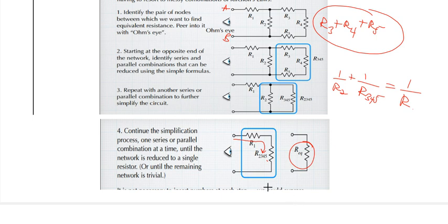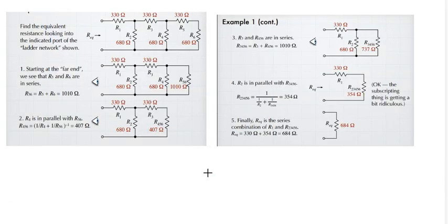So it is simple to deal with equivalent resistance in a complex resistive network if you are able to, first of all, identify the terminals between which you want to take your resistance, and then two, begin to resolve from the other end by dealing stepwise with any series combination you come across or any parallel combination you come across until you attain the final resistance value.